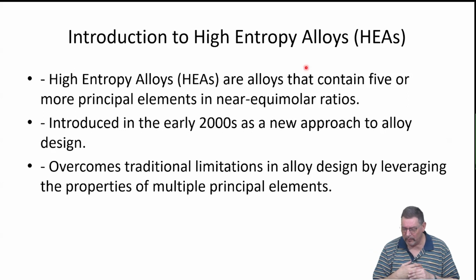And then if we want a high entropy system, only a single phase solid solution, the compositions need to be varied a little bit, so that it's no longer totally ideally equimolar, but it will still have large relative concentrations, meaning that there is not a minority element present, but all of them are real alloying additions with equal rights, so to speak.